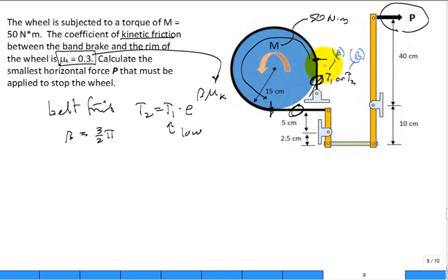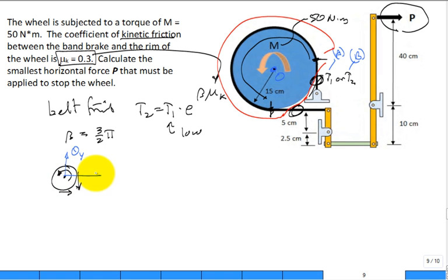If I cut through that belt, through the air, through this belt, through the air, I can create a free body diagram. The free body diagram will be a circle. It'll have a tension coming down and a tension going over. And it'll have a moment applied. It'll also have a force at this support. Let's call it O. So O in the Y, and O in the X to hold it there. It's rotating on a frictionless pin right in the middle.